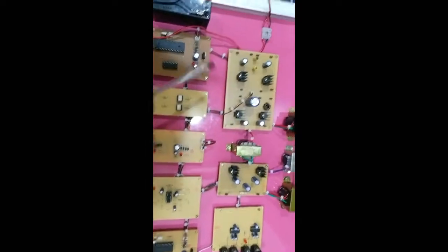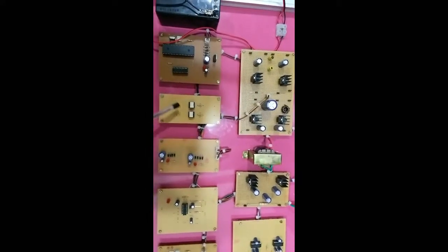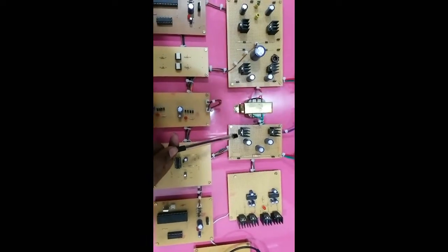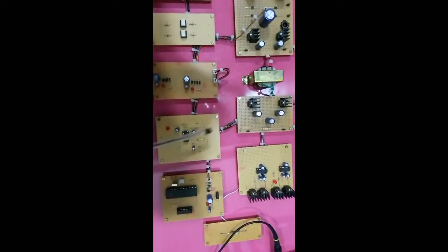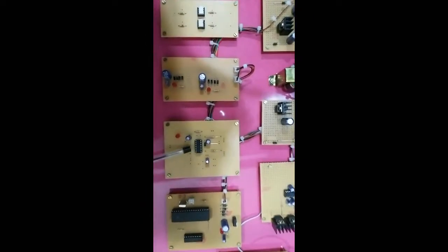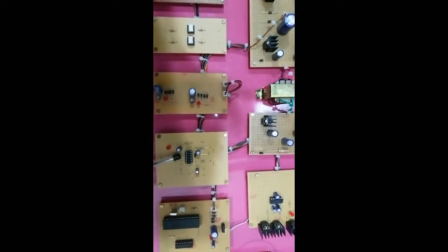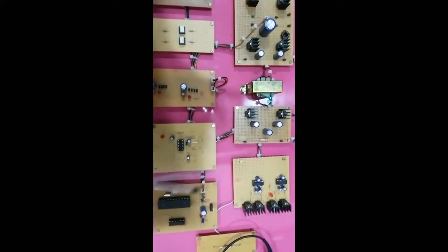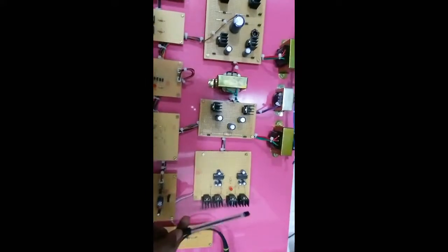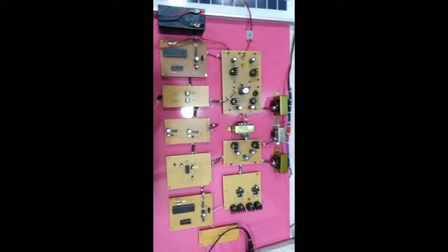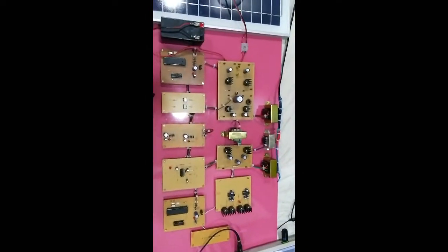So for this main circuit switches, we are having this isolation circuit, and from the transformer secondary side also we are having 2 switches. So for triggering these 2 switches, we are having this PIC controller IC combined with this buffer IC, and here we are having the gate driver which also acts as isolation circuit. It isolates the main circuit from this programming circuit. For these 4 switches, we are having these 2 gate drivers which provide isolation for these 4 switches. So this is our overall circuit.